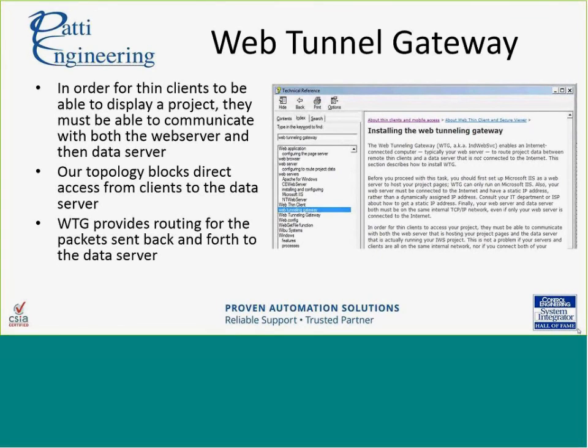But the reason we needed this, in order for thin clients to display a project fully, that device needs to be able to talk to both the web server, which is serving up the web pages, as well as the data server, which is where InduSoft is running. Many times, these are the same box, and so this isn't that big of a deal. But other times they are separate boxes, as in our situation.